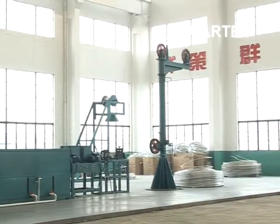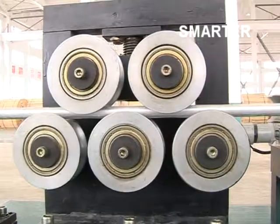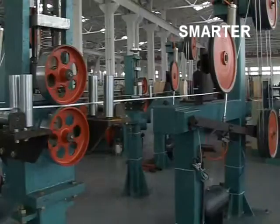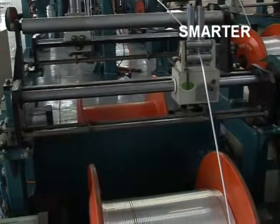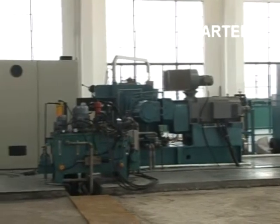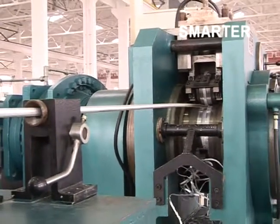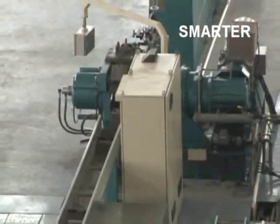The line is mainly composed of payoff, rod cleaning system online, straightener, extruder, hydraulic system, lubricating system, cooling system, meter counter, take-up tension controller, dual-pad take-up, and electric control system. The main extruder consists of the motor, reducer, crosshead, frame, and so on. The main extruder uses a DC motor as a source of power, which is transferred to the main shaft and extrusion wheel passed by the reducer.